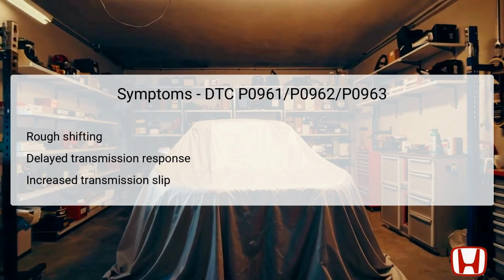Users may experience several symptoms related to the DTCs P0961, P0962, and P0963. One of the most noticeable symptoms is rough shifting. This occurs when the automatic transmission has difficulty smoothly transitioning between gears. Additionally, drivers may notice a delayed response during gear shifts, which can lead to an unsettling driving experience, particularly during acceleration or deceleration.